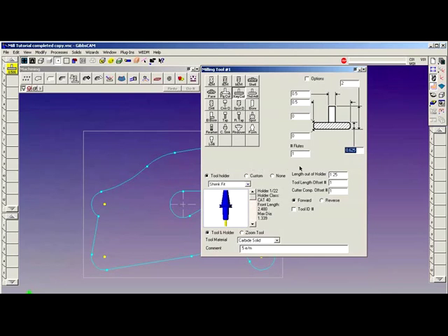As you notice, all these values don't change at all when we change the tool tile. We can always come back and change any of these values as we see fit. A thread mill. Thread mill is very similar to a keyway cutter. Same style of cutter, overall length, shank diameter, cutter diameter, and in this case, we've got the included angle of the thread. In the case of an Acme thread, we type in a 29-degree angle. Number of flutes, and cutter thickness.